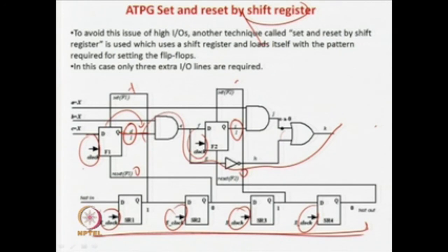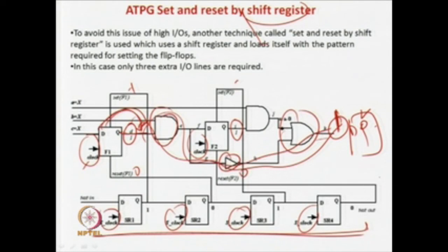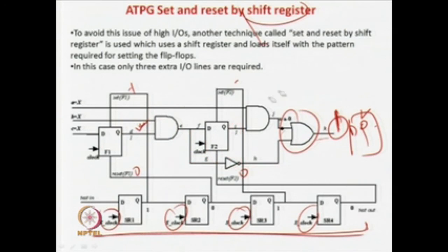So you cannot have a very fast clock over this period, because whenever you apply the clock pulse, your data will come here. Then to get the data here, maybe we can assume there is another flip flop over here. The change in data should arrive over here, and only then can you use another clock to trigger this flip flop, this D Q say. But this is a long path: this output will be there, then this AND gate, then this inverter, then the OR gate, then the data will come. So there will be some delay of the data travelling from here to another flip flop input. So this clock period has a limitation in speed. You cannot go for a very high speed clock over here, so you have to use a slow clock.